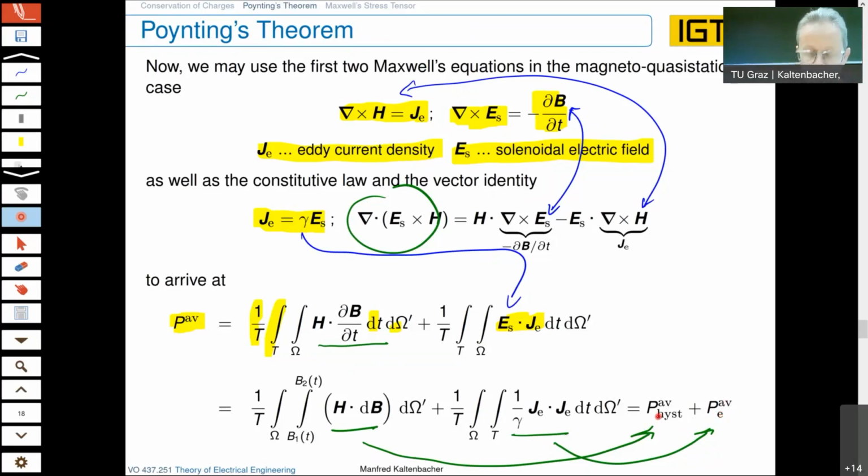This first part, we cannot really influence with the geometry. Here we need special materials. That is also a key part of producers of these electric steel sheets: to make the material in such a way that the hysteresis losses are as small as possible.